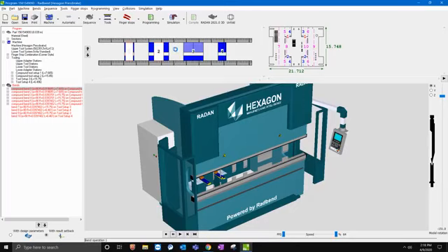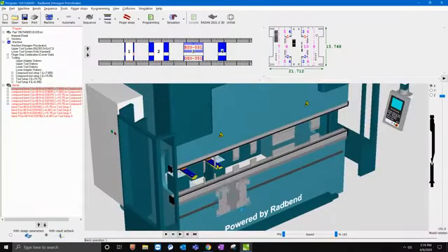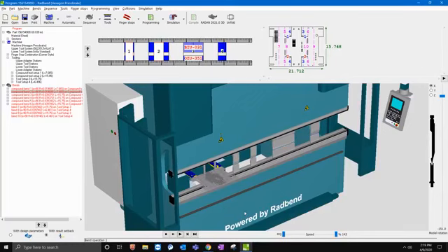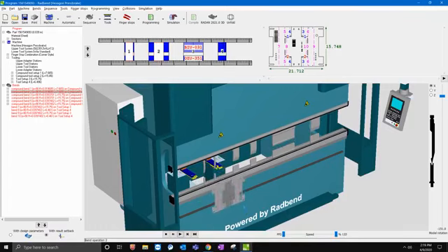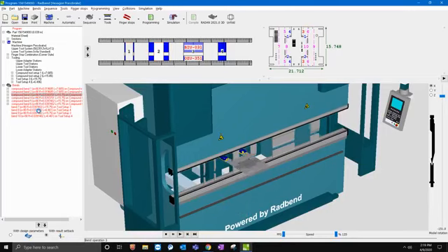So I'm going to hit play on this. We're going to unpause it, hit play, and watch it. I've got material handling on, so it's going to show me, okay, I'm coming down, I'm bending this part, I'm going to turn it around. I'm going to zoom in a little bit, rotate that part around and put it back in, and we'll take those two tools there and bend it, right? As it does that, guys, you can see it's running through that. So let me explain. It's going to move down each bend line and make sure and check that there's going to be no collisions.